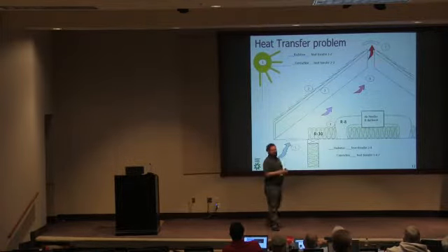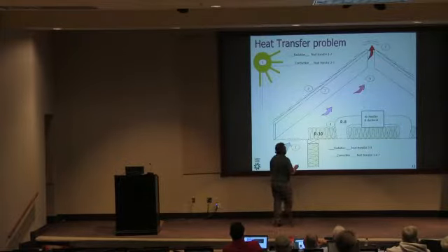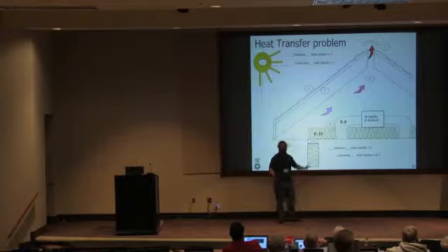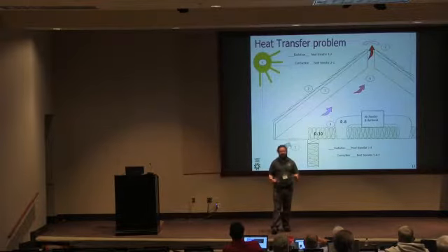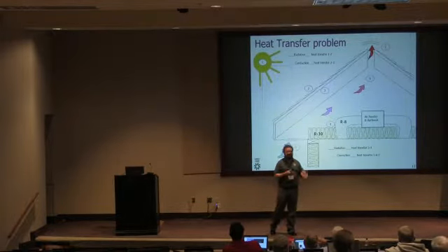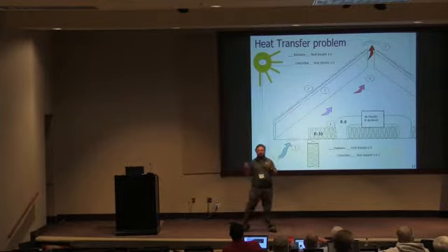You've created more uncontrolled air changes. You're putting your home under negative pressure, which we certainly don't want to do in a warm, humid climate in the summer. But hey, your attic is now 10 degrees cooler. So we think power attic ventilators are actually a really bad strategy, if you're going to vent passively. Power attic ventilation is actually banned by the current Georgia Energy Code, with the exception of solar-powered power attic ventilators. But don't do it. It really is not a strategy that benefits the home in any way.